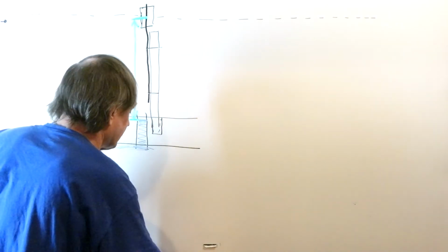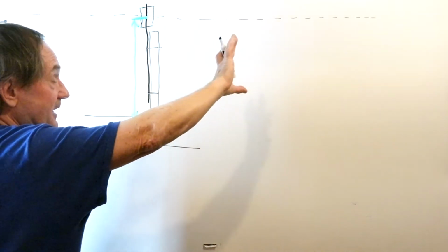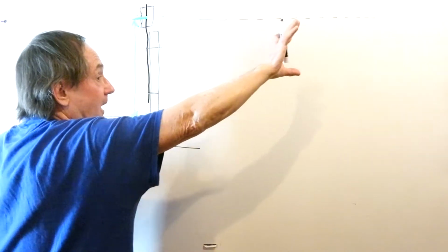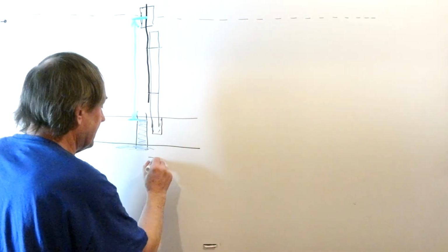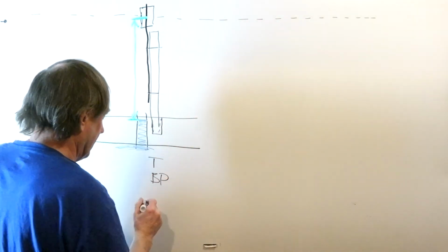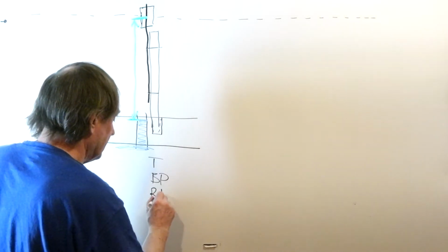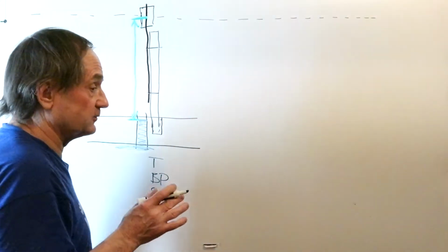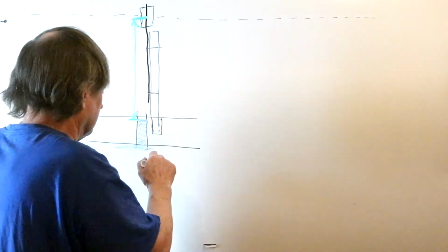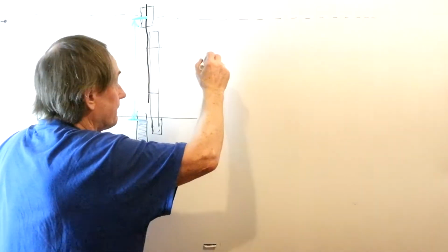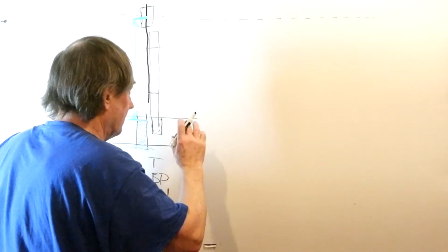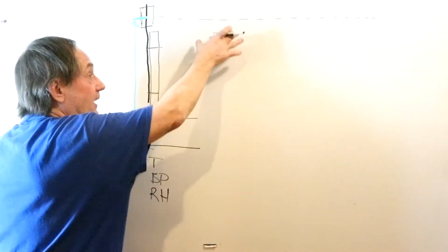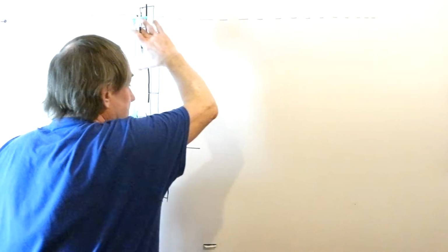Also, when making these measurements along the optical corridor that we're sighting, every half mile we'll be making temperature measurements, barometric pressure, and relative humidity. For the temperature, I have a thermistor stick, I'll show you in a moment, that gives us the ability to measure the vertical temperature profile of the optical corridor that we're sighting through.